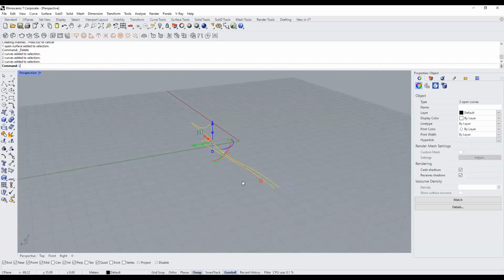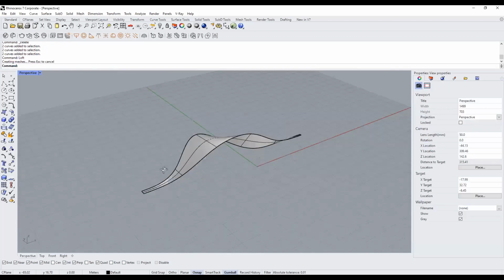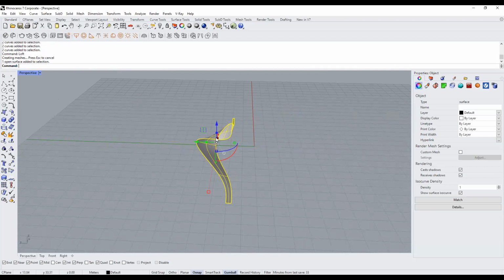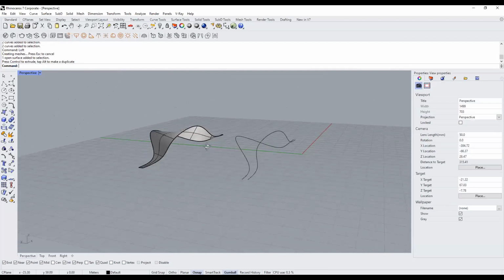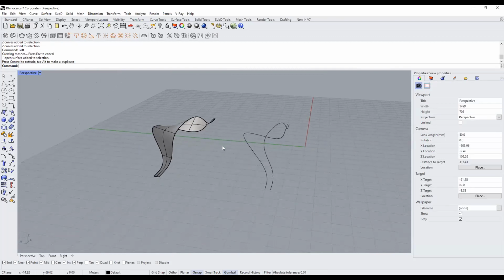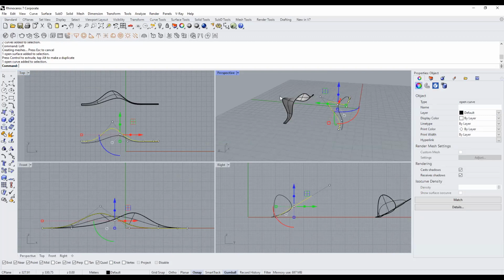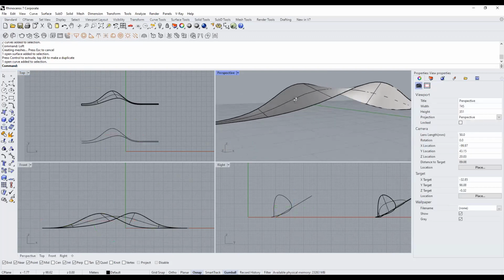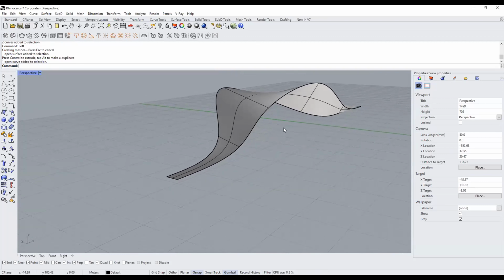And then just select the curves, use the command Loft, hit OK. I'll get something like this. That's it. Now, I was saying how you can have multiple curves as well. Let's try a small variation to it. I'm just going to move this aside as maybe the first experiment. The variation, what I'm going to do is add another curve to this. So if you look at the surface right now, if I were to consider it as an architectural element, it looks more or less like a roof surface.